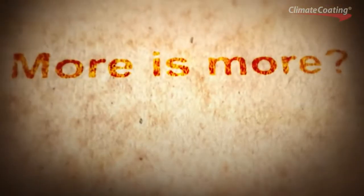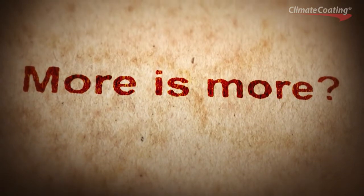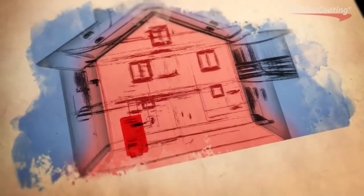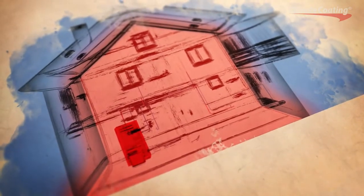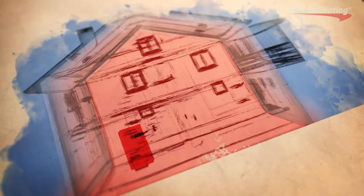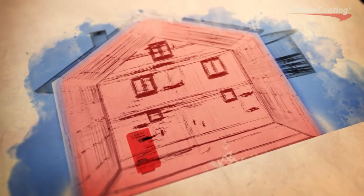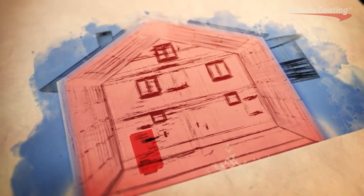So in order to get the lowest U-values, the heat resistance of the shell has to be improved. Subsequently, the energy consumption falls. This may occur when an additional layer of insulation is added to the existing facade, or if during construction, materials are used that offer better insulation value.